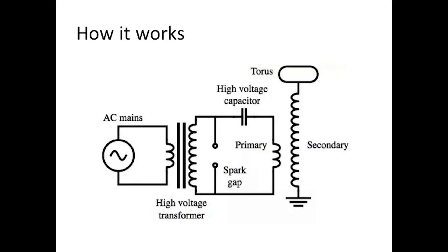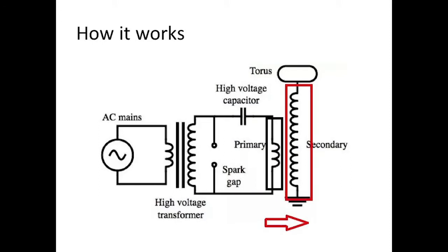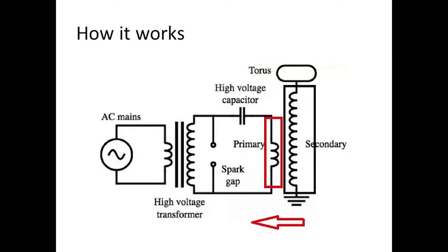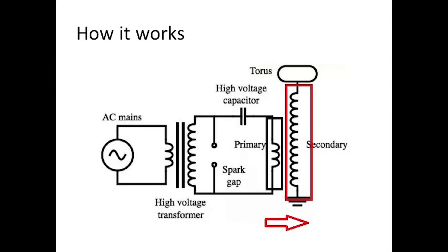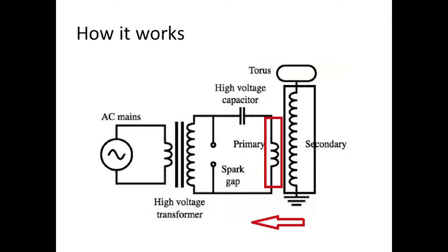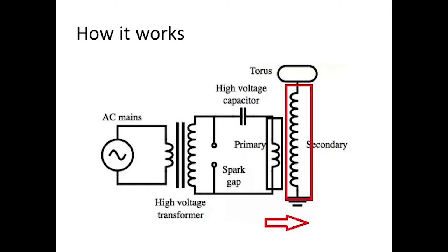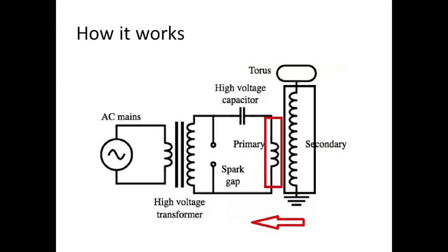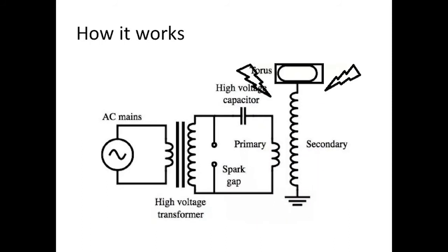So how does a Tesla coil work? Tesla coils start when the circuit swings the charge back and forth between the primary coil and the capacitor, while the secondary coil and capacitor resonate with the former through many cycles. The primary coil transfers its energy to the secondary coil over a number of cycles until all of the energy is transferred out of the primary to the secondary or to other energy losses.